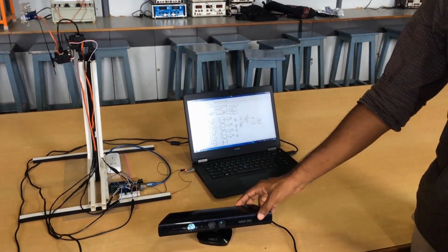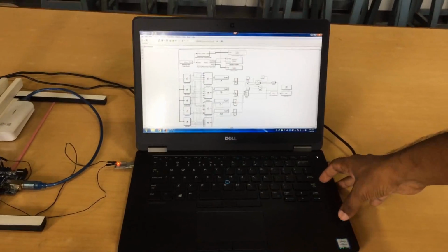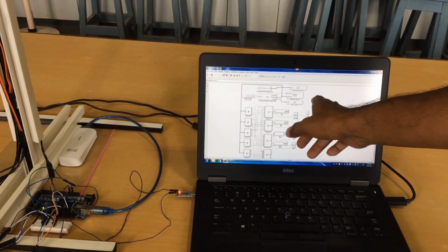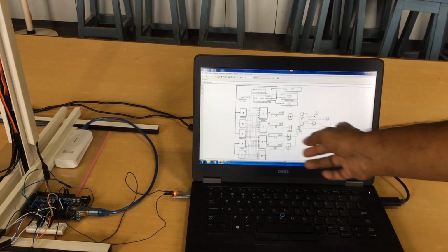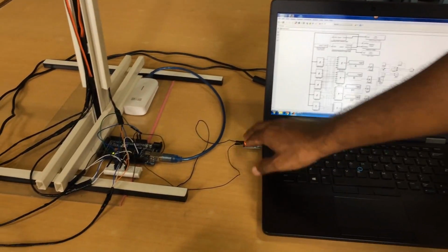The Kinect tracks the human skeletal joints and transfers it to MATLAB software. In MATLAB, we acquire the required skeletal joint XYZ coordinates data and convert it to angle using a vector equation. The converted angles of the joints are then sent via the serial communication port.